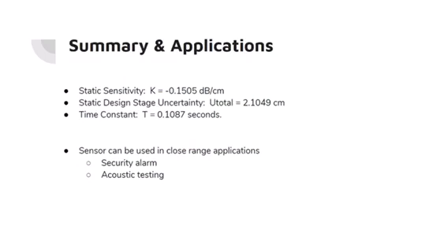Summary and applications. The static sensitivity of the system was negative 0.1505 decibels per centimeter. The static design stage uncertainty was 2.1049 centimeters. The average time constant was 0.1087 seconds.